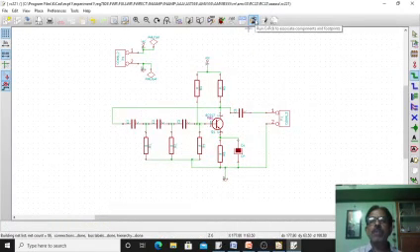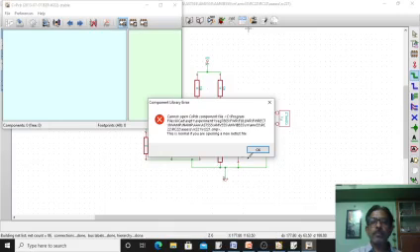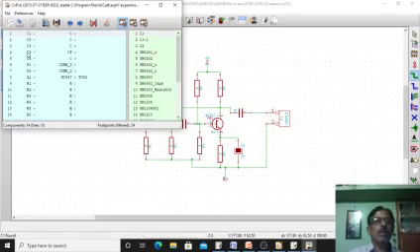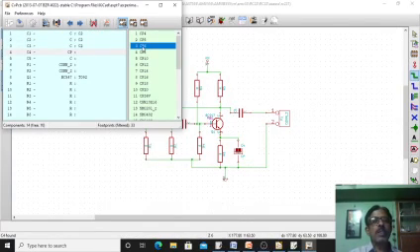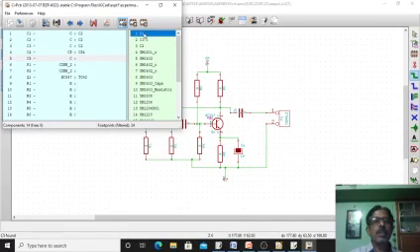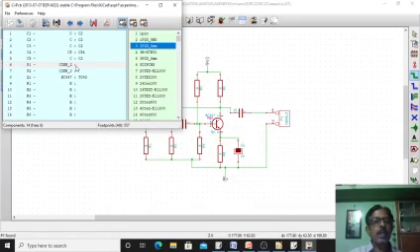Then you do the association of the components. Here the association will come. For each capacitor C, let us take C2, or you can even take C3, C4 or anything. For the polarized capacitor CP you take CP4, and again for capacitor C I am taking C2. For connector 2, I am taking it as SIL2.